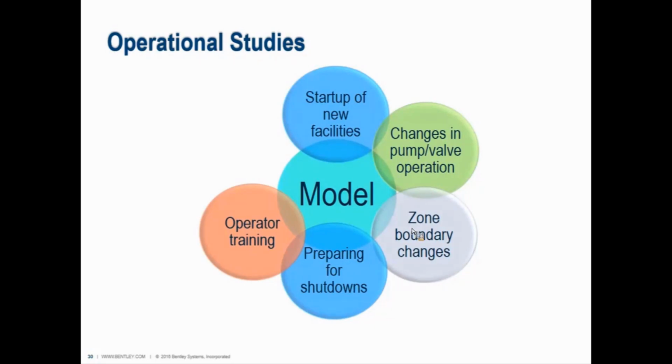Or you can think of the model as a flight simulator, if you will, because with pilots, you don't just toss them the keys to a 747 and say, all right, off you go, go fly, without some type of training. So in this case, the model can actually be treated as operator training, to sit a new operator down in a chair and show them exactly what happens if you don't turn the pump on at 3 o'clock before the evening demand hits, because all the tank water level goes away in all of the tanks or something. That way you can show how to break things or not do certain things in the model and not have everyone experience that negative side effect out in the real world. So think of it as a simulator, if you will.